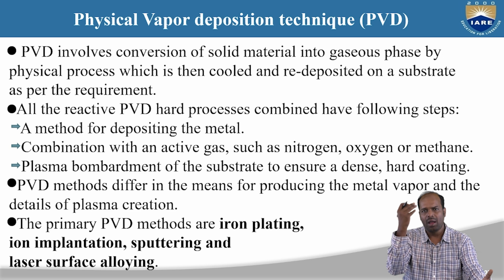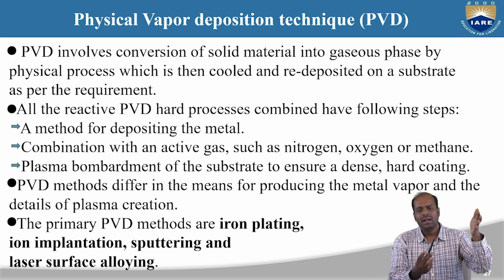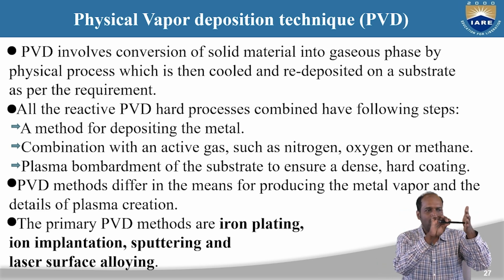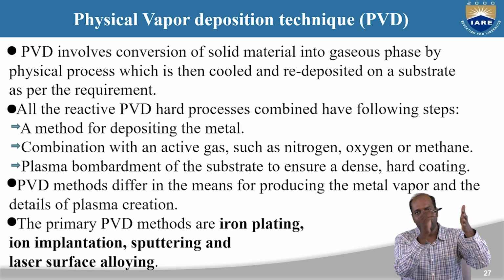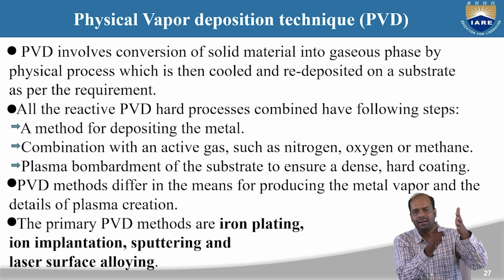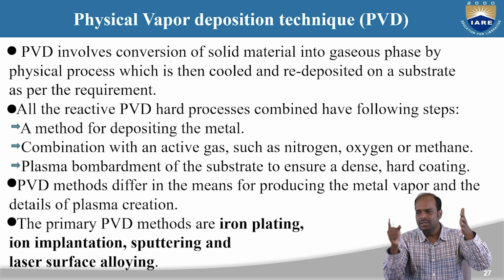Due to the plasma, argon ions go and collide with the compound, and because we created the vacuum, the collided particles can travel directly from the target to the substrate.